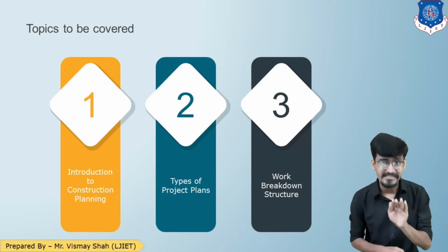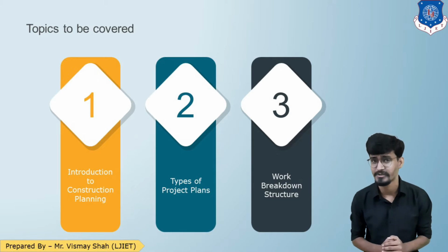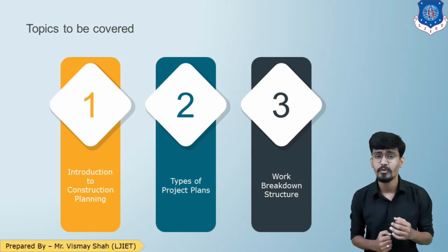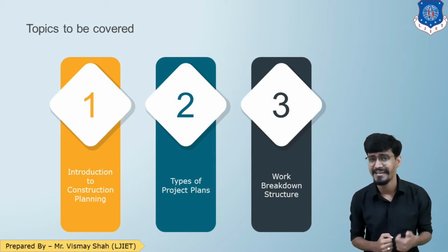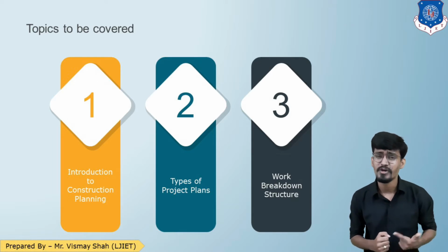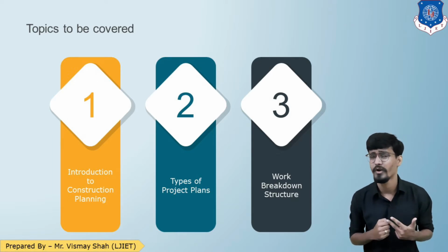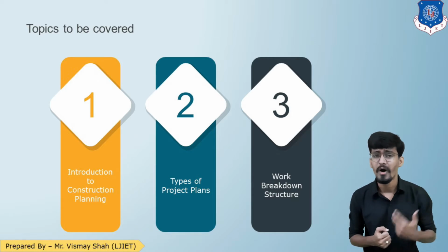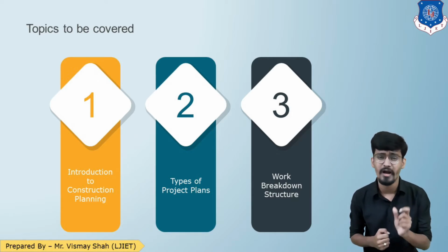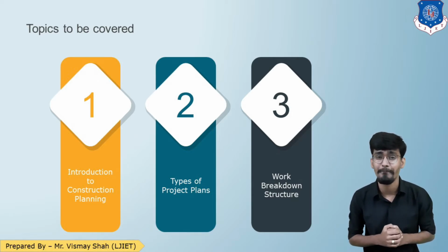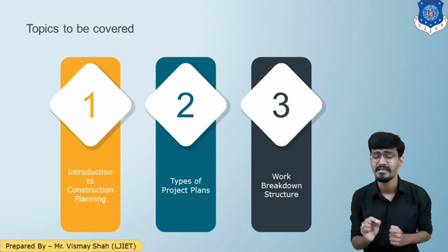That is our first step towards construction management, you can say that. So we are going to learn about introduction to construction planning, then types of project plans, and then work breakdown structure. In short, we call it WBS. W, work, B, break, S, structure, work breakdown structure.